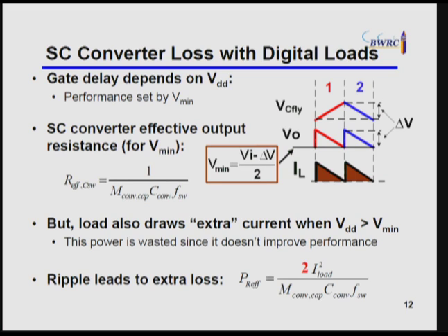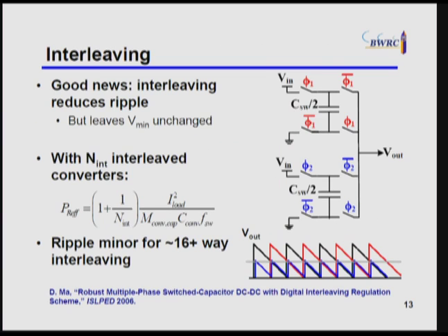Okay, so that's kind of bad news because especially in this integrated context where it's all about how small can you make that converter to fit it into the rest of the chip, you're basically doubling the loss that you get from something that's already pretty much your dominant loss term. The good news, however, is that it's actually fairly straightforward to fix that problem, okay?